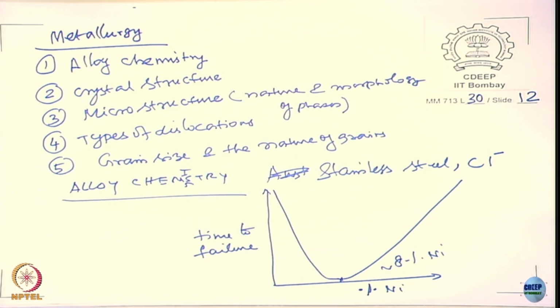If I add nickel, you will see that the stacking fault energy decreases. So, they are going to have different dislocation structure. They are quite intertwined, but still you can try to make some component of what really happens to the SCC from that point of view.